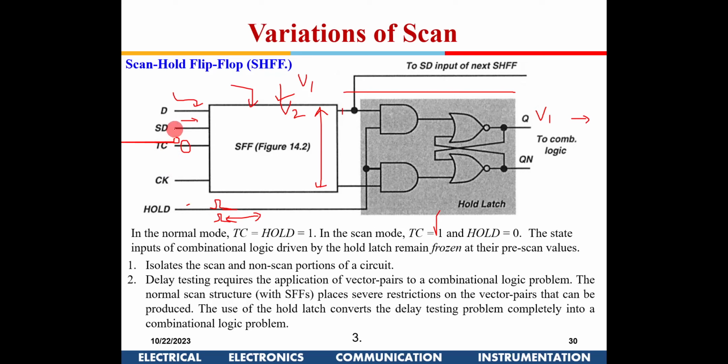But even if I put it into normal mode, data will not be captured here. So I will capture the data after giving this clock signal high. After this second hold, the duration between this hold and this clock will be 1 clock period. So after applying the new test vector v2, after a time period t, this clock will go high, and these flip-flops will capture the new value. And it should capture the new value.